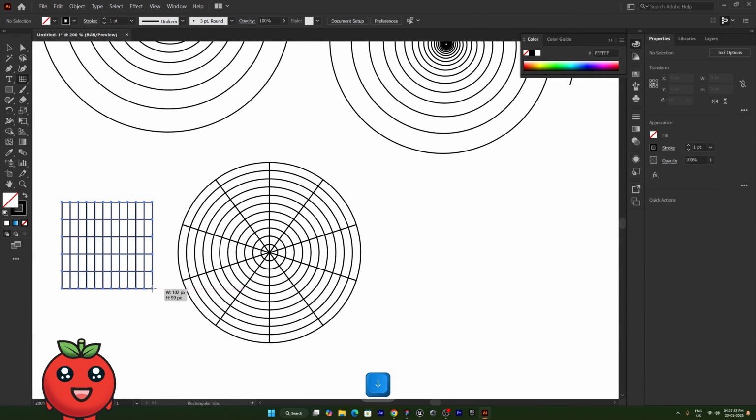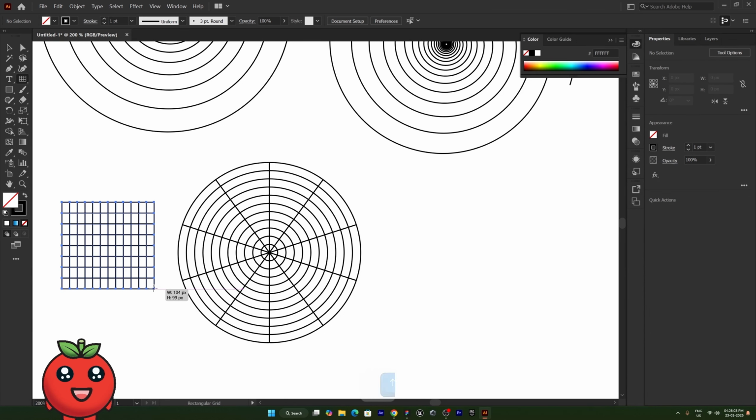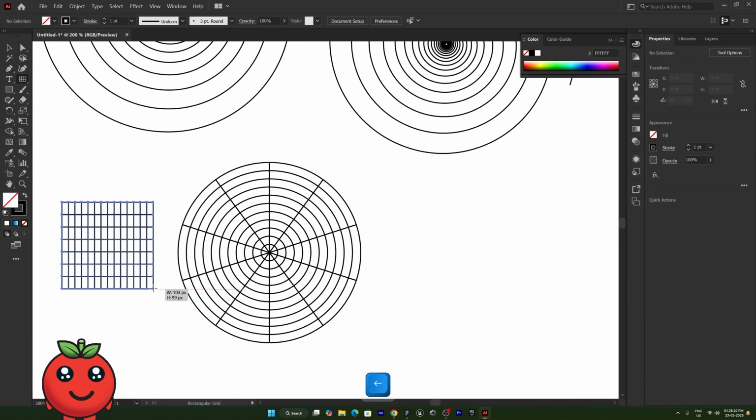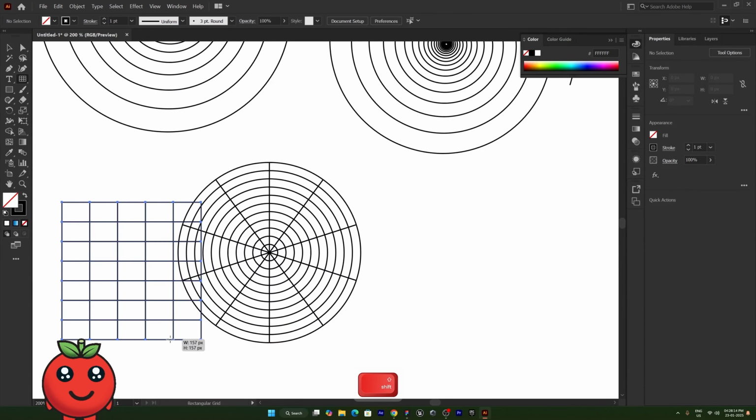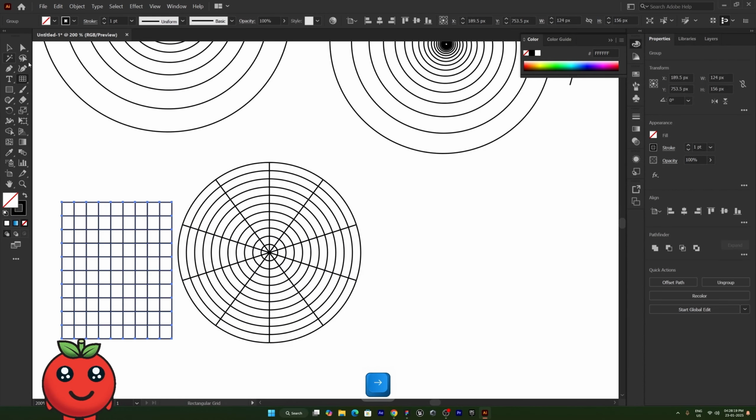Hey, we can increase or decrease grids over here also, like this with the arrows in the grid tool. Sorry, I forgot to tell you about it. Sorry. It was a shortcut. You can increase or decrease the grid size like this. Very easy. And always hold shift for this. So these were very easy line tools we get in Illustrator.